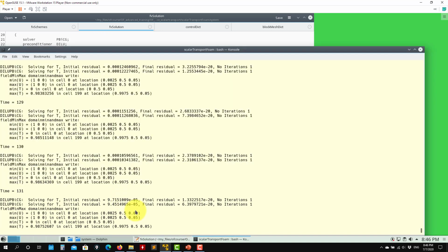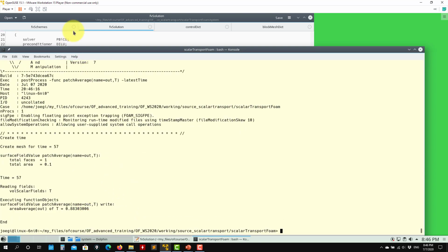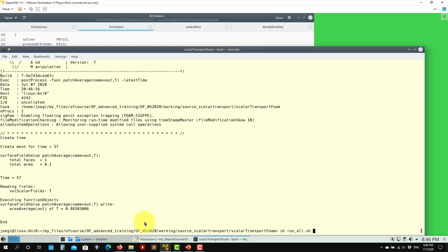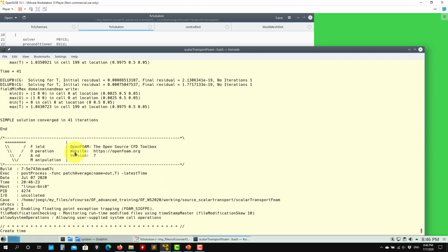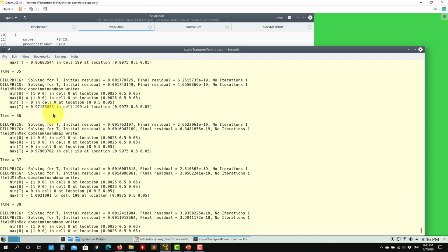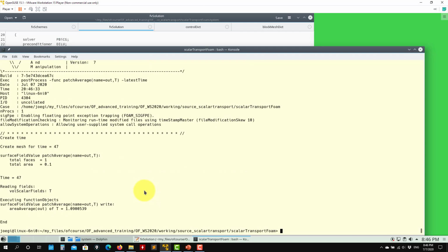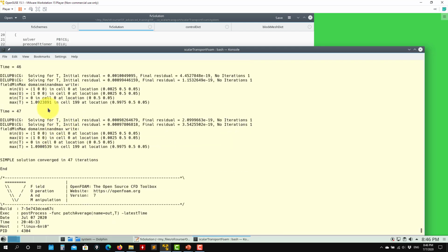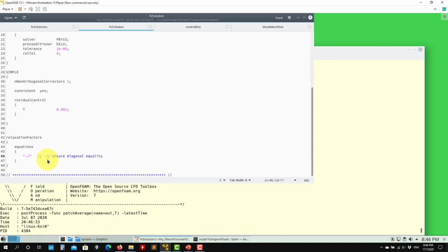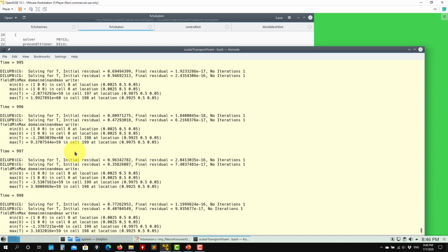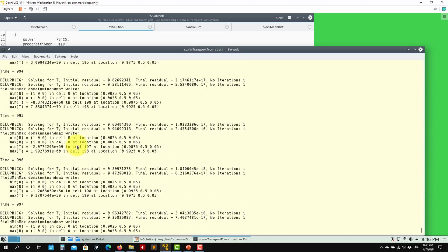Okay, so let me put this one there. And if I go to 0.9, see that now it's getting to 1, but it has those oscillations. And as you go to 1, we are going to exacerbate those oscillations. See that here we're at about 10%. And remember that it's always possible, instead of under-relaxing, to over-relax. It's not recommended, and actually it's not a good standard practice. And seeing that in this case, it is iterating, but it's converging to a wrong solution.